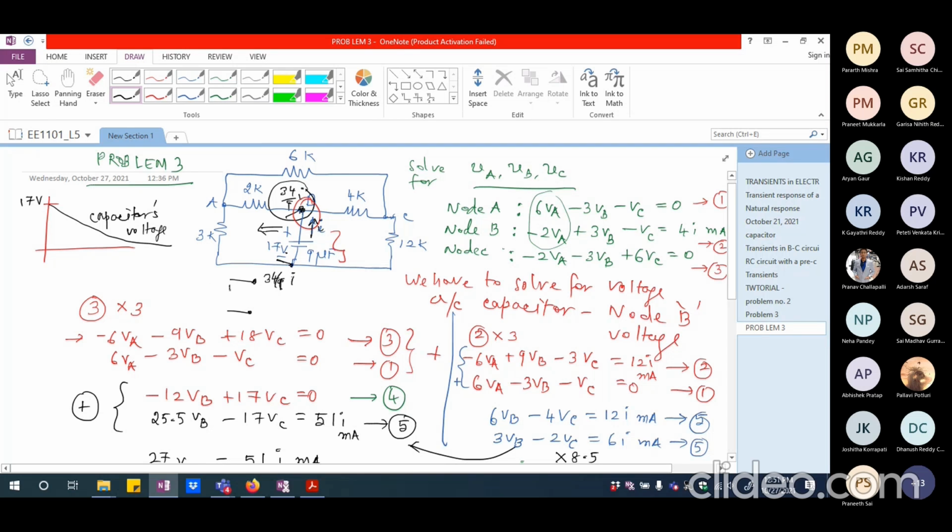And what is the current that is flowing here is I. So what is visualized as the impedance across these two terminals? That is the voltage divided by the current itself. So voltage divided by the current, that is 34 by 9 K, because we said the current is in milliampere. So that is the reason why the impedance visualized across these two terminals is the resistance being seen by the capacitance itself, which is connected across these two terminals.